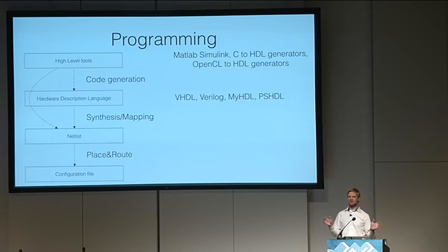that placing the resources on an FPGA is an NP-complete problem, and so is fitting it into the timing that you're setting. For example, at one point you say, I want to run this design at 100 megahertz. And the worst thing that could happen is that it sees it can fit all the logic into the FPGA, but the frequency is like 95 megahertz. And so it's routing up, throwing away stuff and trying out new ideas to see if it fits or not. And the fun thing about it is that it depends on the seed.